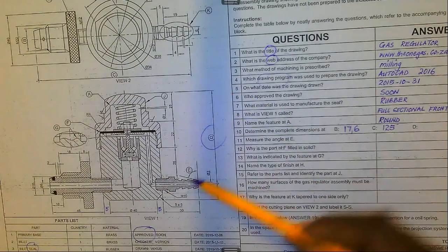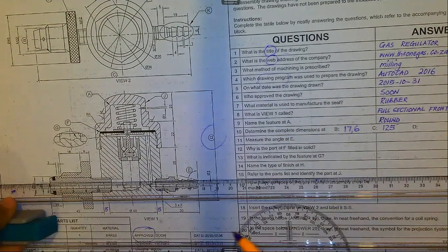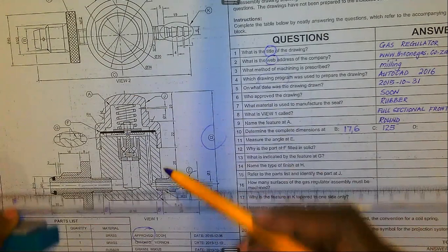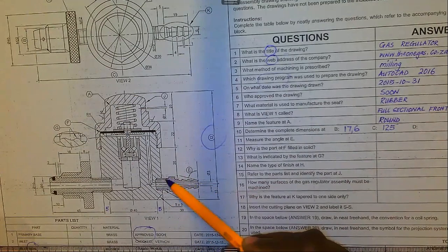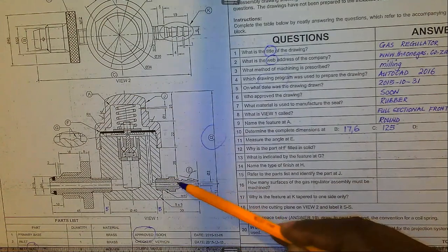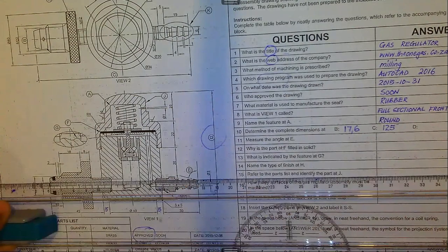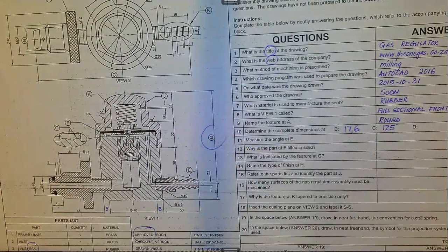So what we need now is, if we want the distance from here to there, to the center line of this, but this one is said to be M10. If we check even with our T-square, that's the distance it's going to get us to. So if this is M10, from here to there that's 5 millimeters, okay? Remember, when they say M10, 10 is a diameter. So to get to the center line, we need 5 millimeters. It's not here, it's right there in line with the M10. So 5 millimeters plus all that should give us something. So we'll say plus 5.